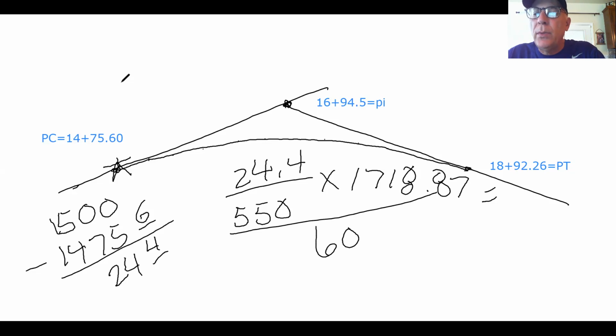something with the decimal. What you would want to do then is convert that decimal back to degrees, minutes, and seconds. And our first deflection would be 1 degree, 16 minutes, and 15 seconds. Okay, so that being said, that would be our answer for letter F. I'm going to go through and erase now.